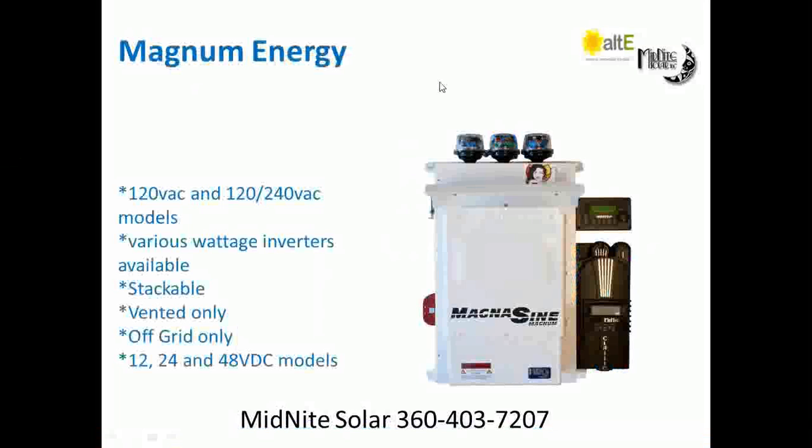And Magnum Energy, undoubtedly probably one of the more affordable inverters out there and more versatile, I guess you'd say. It does not grid tie. I want to point that out in big, bold letters. Does not grid tie. It will use the grid to charge batteries, but it will not sell back. They have models in 120, and they have models in 120/240. They have models in 12, 24, and 48 volts. The 120/240 only comes in 24 and 48.